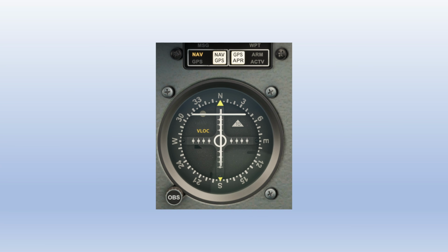When you're receiving a localizer transmitter with a traditional VOR receiver and display, turning the OBS knob does not affect the course indication like it does with a VOR, since there's only one course being transmitted. Good operational practice is to select your inbound course as a reminder, but this will not affect the course indication.